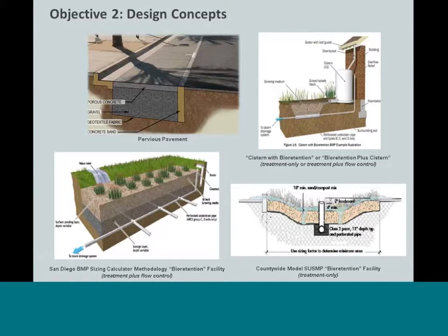The lower left is another bioretention facility with your typical soil media layer and aggregate below there. So if you have a lot of storage volume requirements, then by extending that aggregate across the full bottom of the bioretention soil mix, you're going to get additional storage volume. Whereas the graphic on the lower right, perhaps there's not as much volume in the design requirement.